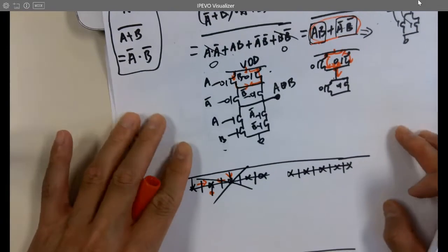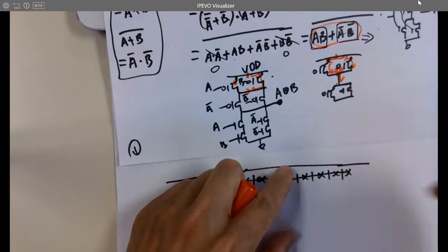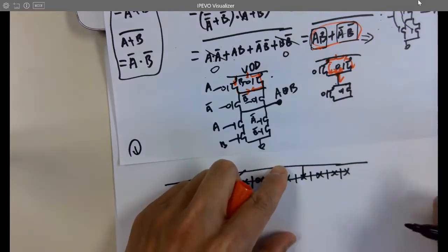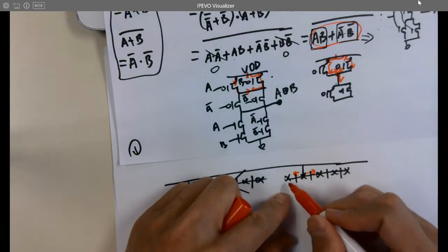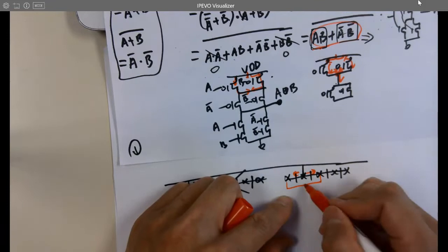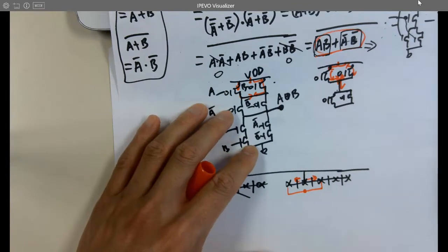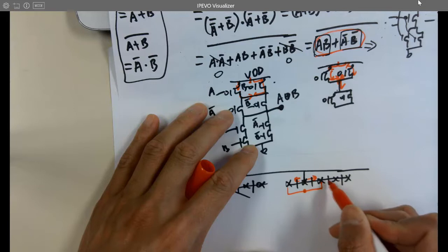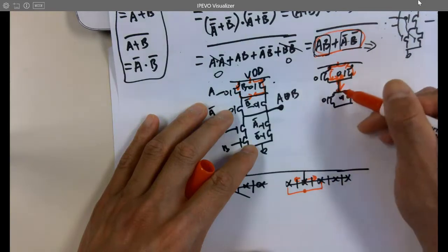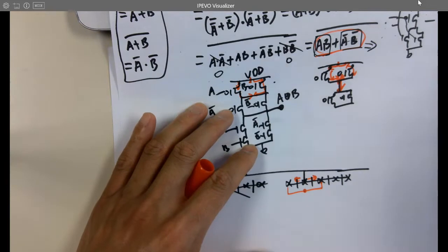So what's the alternative way to do it? We want to introduce 2 wires here, right? Can I introduce just 1 wire, and then split into 2 branches and merge? So this point becomes this point right now. Make sense? Then what's next? This may work because this is a point that merges, and here is the drain of one of the two PMOSes, which makes sense. It's not shorted to VDD at least. This one is somewhere down in the circuit.